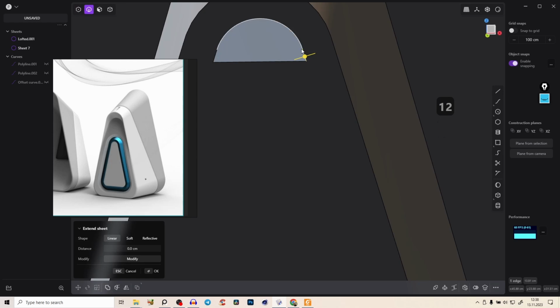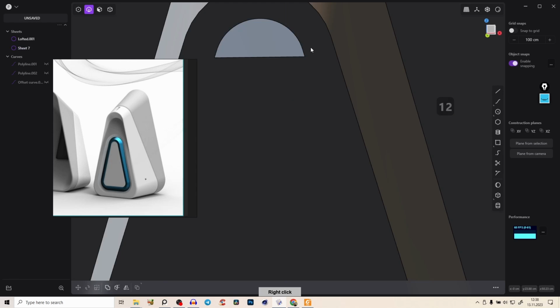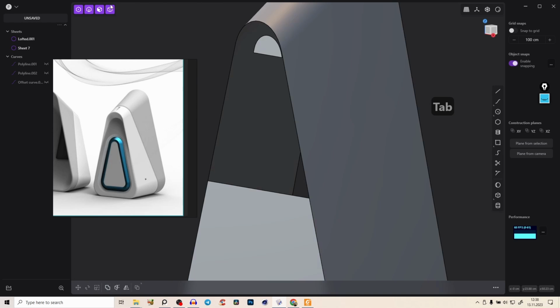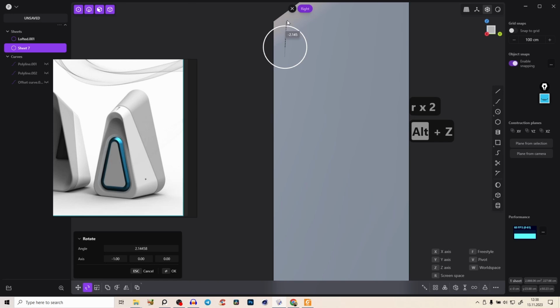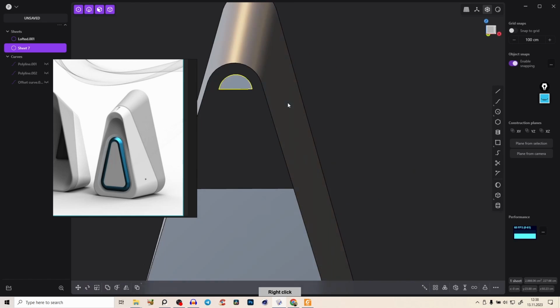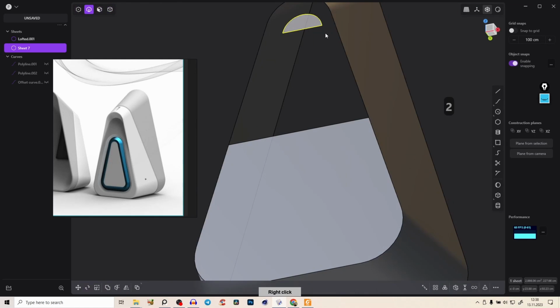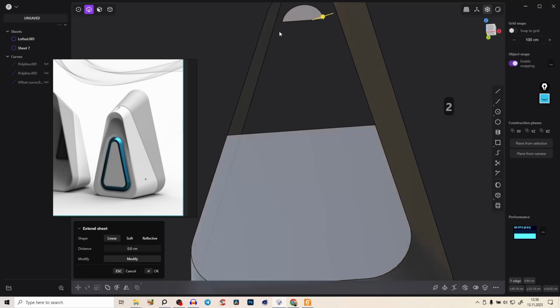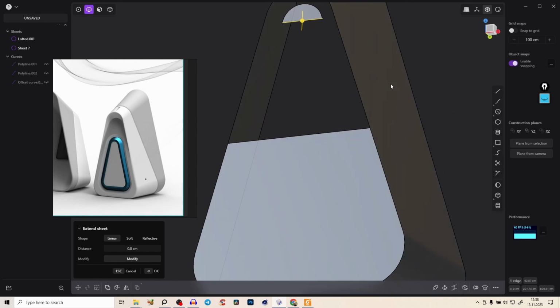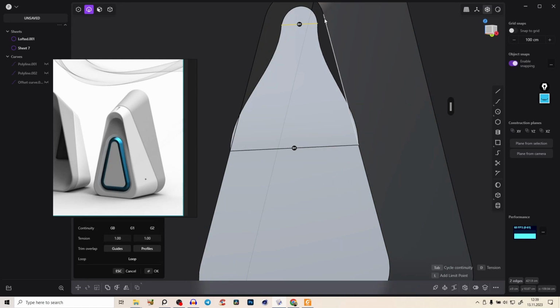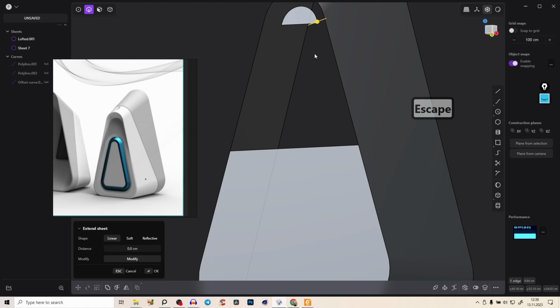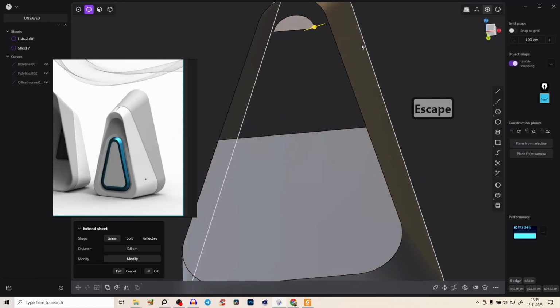So before we go to this point, we can make it even shorter. Because also press Tab, object mode, and Alt Z. Let's rotate this a little bit, because you see it's inside a little bit rotated. So just rotate this a tiny bit and perfect. So now maybe that doesn't make sense at all, but now we will reconnect it and rebuild it. So you see we can loft those edges here, but we are getting a very weird shape. So for this example, we want to create some guiding curves that we will then push the surface in with.